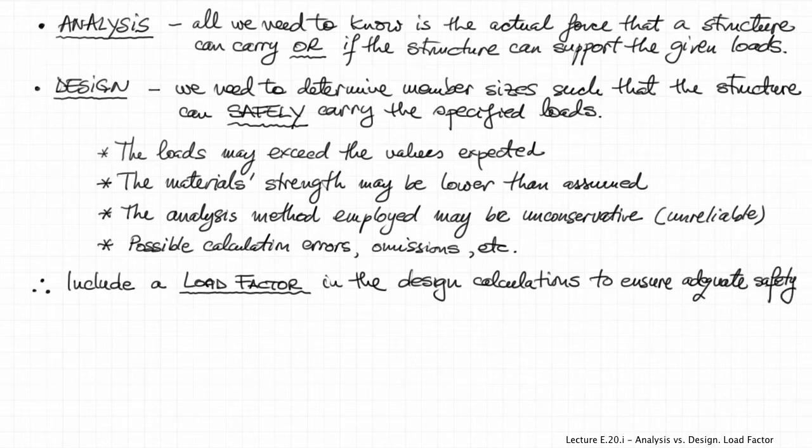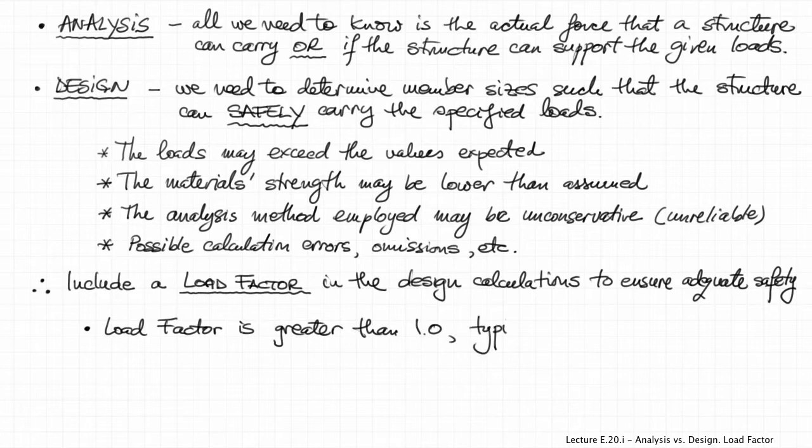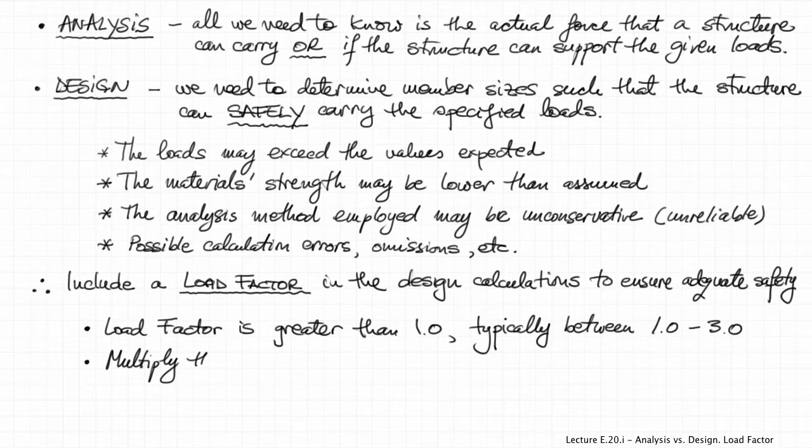Now, in order for this to work accordingly, the load factor is typically a number that is equal or greater than 1. For example, typical ranges are between 1 and 3, and these values are given in design standards. So they're already specified, and the design engineer will obtain them from the design standards and use them in the design procedure.